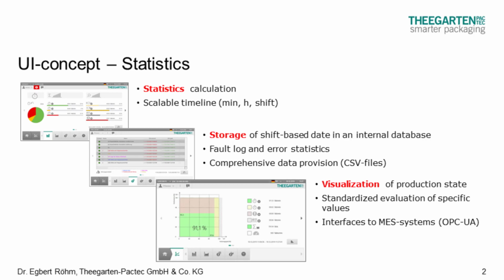An internal logbook stores all data defined as relevant and keeps them ready for a possible data transfer. The compression of this data on the time axis can be scaled individually. Finally, the stored data can be processed into key figures and presented graphically. The user interface offers visualization tools for this purpose. It is also possible to transfer aggregated data to an MES system via the integrated OPC UA interface.